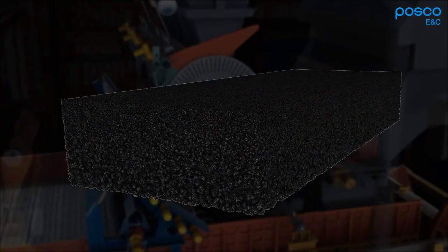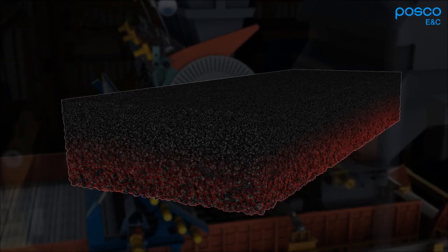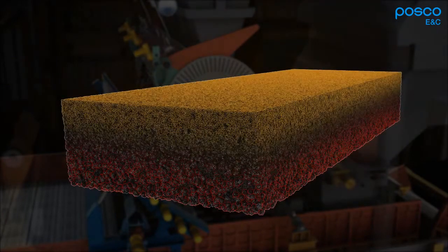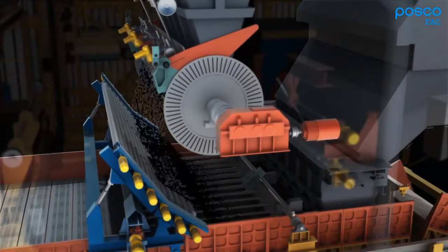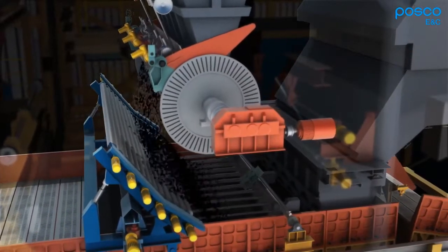It is a core technology for designing the charging equipment that mixed materials are evenly charged in a horizontal manner. Lump grained materials are forced to be charged onto the bottom, and fine-grained materials onto the top of a pallet. This helps improve permeability in the bed and make materials burn evenly.